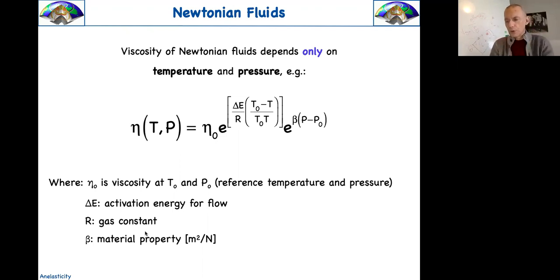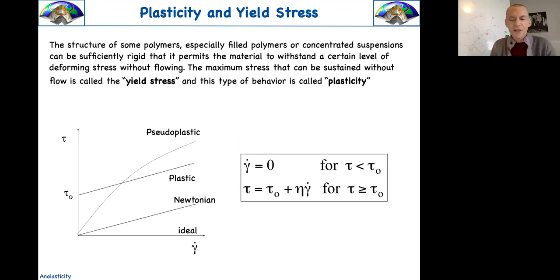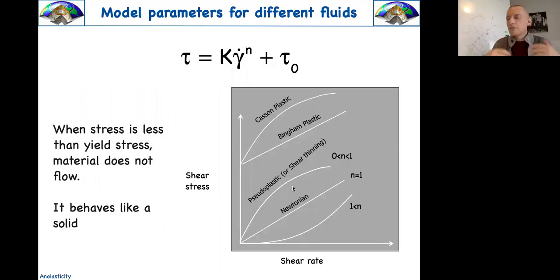Just to remind you that what we're going to use today is a simple version of a rheology that could get very complex. For example, you can study other than simply linear rheologies when you consider shear stress and strain rate. We are going to use a Newtonian one today. The ideal, no reaction, but you can have plastic behavior, and so you get a reaction only when you overcome what is called yield stress. So nothing is happening, then you overcome it, and then you're going to be plastic. You can mix them, you can call them pseudoplastic. And so there is a whole world of different rheological animals. Again, we're just going to use this, but remember that you can generalize them, and you can get some very nice rheologies that are typically studied in material science.